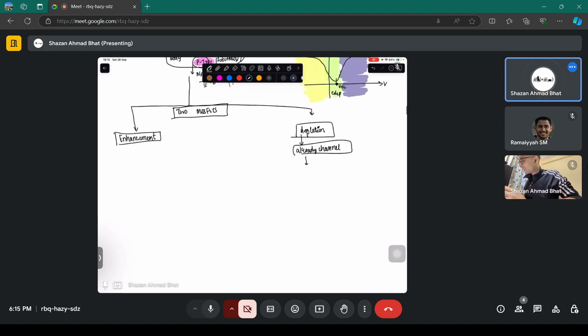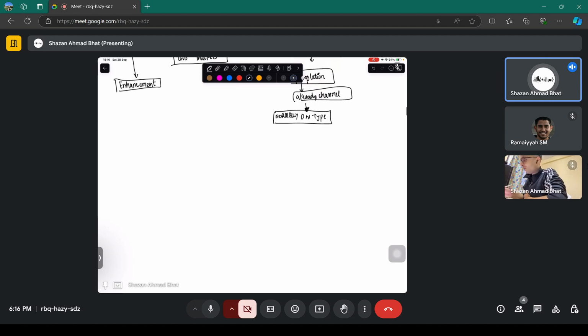That's why this type of MOSFET is called a normally on type MOSFET. It's usually on, so it's not mostly used. In some applications it's used, but most of the time it's not, because you have to apply the voltage to turn it off. That results in continuous power management issues because it's on almost all the time.